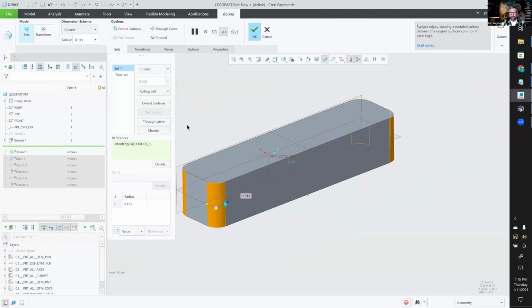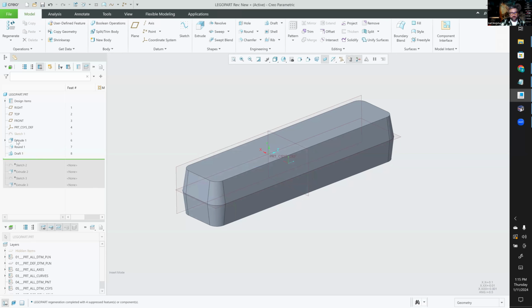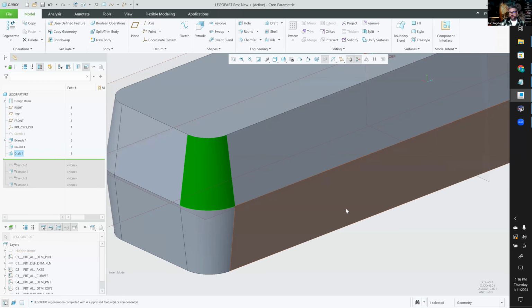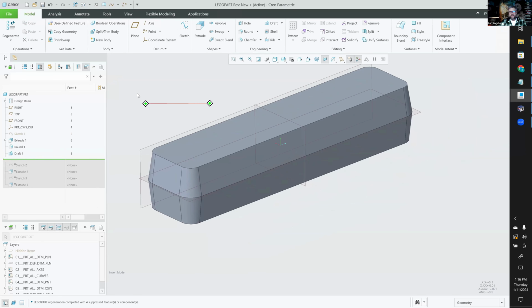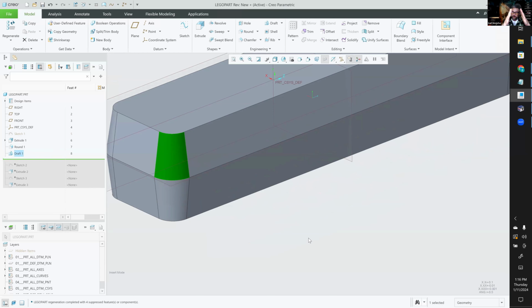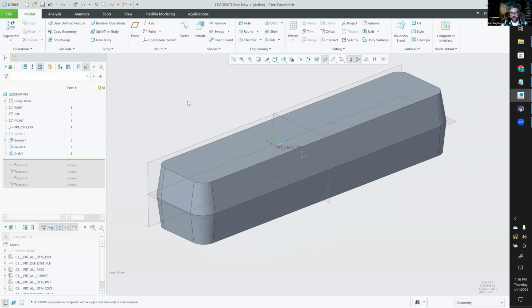So that's probably one of my only superhero powers. I remember when that was new. And then my draft angle, the draft didn't fail, and the draft split now creates a tapered round. So depending on the DNA that you're trying to deliver through to your product, that's a big deal, whether it's tapered or parallel. And we use the term DNA because a Dell laptop has parallel specular highlights, and an Apple